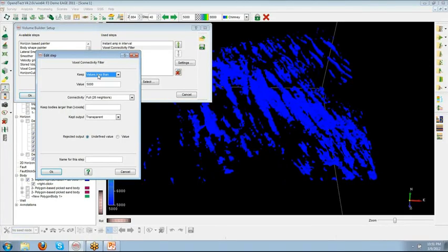And then you can choose that the output body should be the amplitudes less than the threshold. And that would be if you would have, for instance, a similarity and you would try to locate low similarity values, you could use a value less than. But we are working with high energies and we are trying to locate the high energies, so we'll set this option to values more than. In that case, the output body will be the envelope of all the high amplitudes with a limit set down to 5,000.